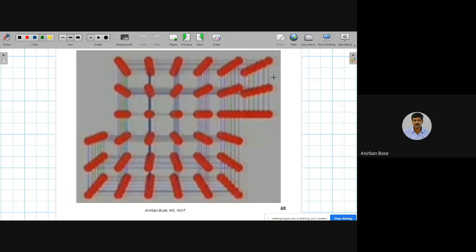When the dislocation motion started and finally it is getting out of the crystal, completely going to the surface, you see that a permanent deformation of the whole crystal has taken place. This is, remember, the plastic deformation. This is irrecoverable. This is an irreversible process, because some thermal energy that is lost cannot be recovered.